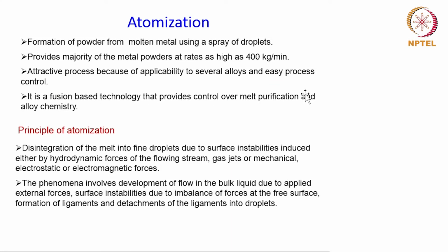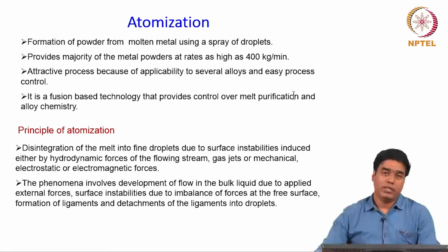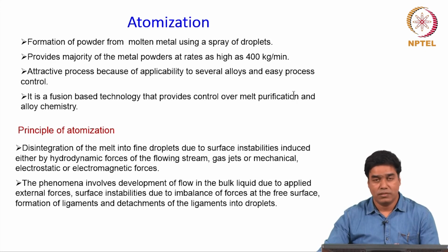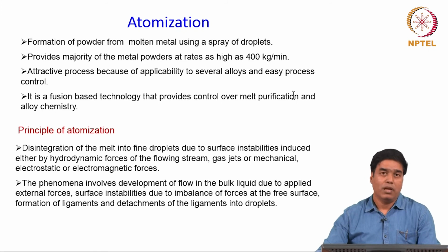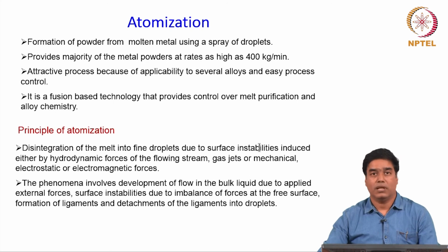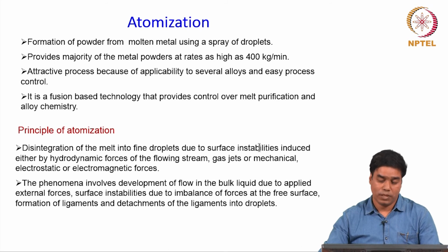The process of atomization is nothing but formation of small droplets of a liquid, and these droplets of liquids are actually generated from a stream of metal with the help of some external mechanical forces which would create some instabilities on the surface of the liquid stream and break it down into finer droplets.